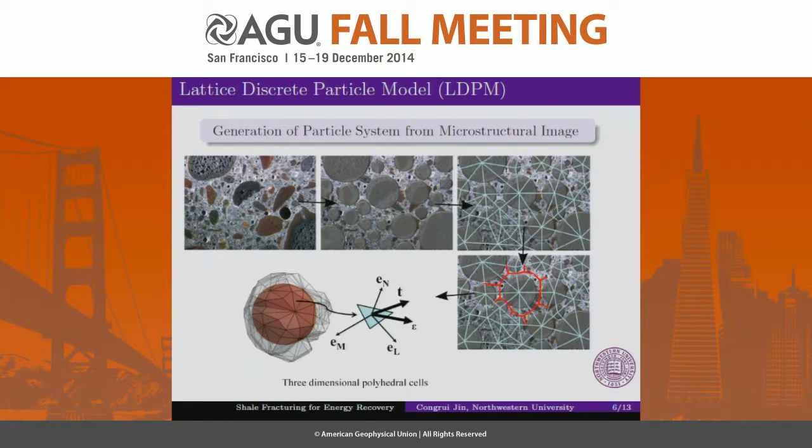The adopted tessellation procedure makes use of well-established packing algorithms for no-contact spherical particle placement and the Delaunay triangulation of the particle centers, and finally the non-overlapping volume tessellation by constructing a dual tessellation to the triangulated domain. The last step defines the surfaces through which the interaction forces are exchanged between adjacent particles, which corresponds to the damage localization zones.